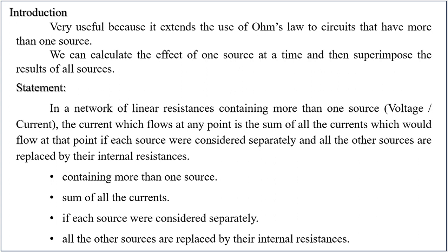It is a very useful theorem because it extends the use of Ohm's law to circuits that have more than one source. We mainly apply the superposition theorem to a circuit having more than one source. We can calculate the effect of one source by considering one source at a time and neglecting the remaining things.